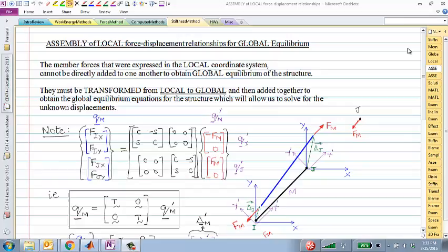You looked at the few examples of the indeterminate trusses that are also available in the codes. There are two ways you can treat redundancies. One is a redundant element, and the other is a redundant support, right? So the same problem can be solved in many different ways by choosing different redundant elements, or actually not choosing any redundant element, but instead a redundant support. You have to make sure on paper that the redundant element that you're choosing makes sense. It should not be that you choose a certain redundant element that still leaves the remaining truss indeterminate.